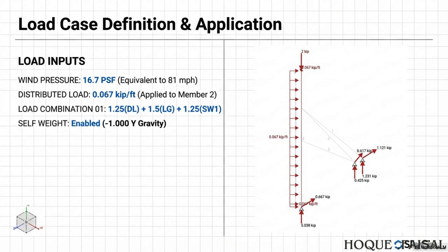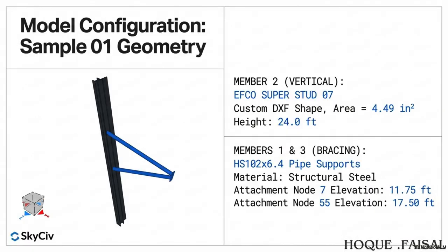That's exactly it. The computer's logic was, oh, I don't need to bend the beam very much because this magic joint is absorbing all the rotational force. It's like the joint became a superhero. It did. It magically absorbed the energy into this fictional fixity. That is why you got that ridiculously small 0.0077-inch displacement. The model was cheating gravity.